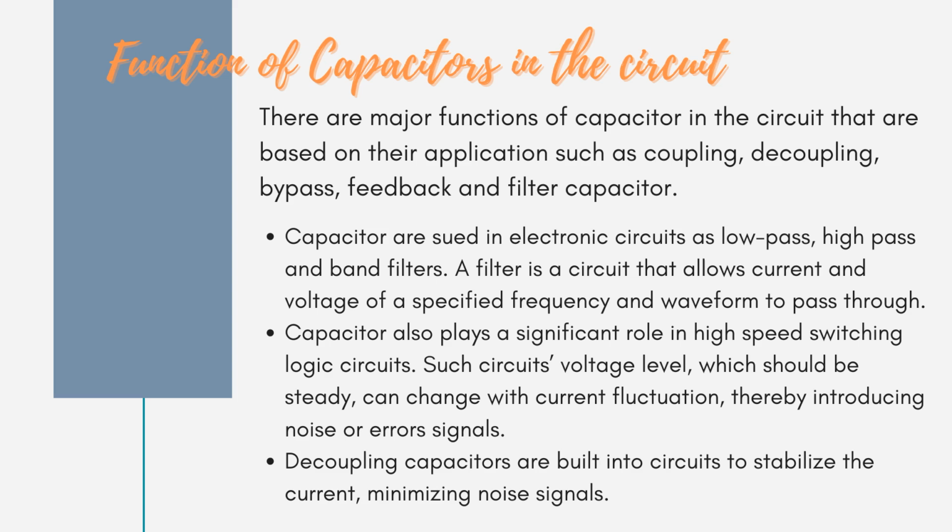1. Capacitors are used in electronic circuits as low pass, high pass, and band filters. A filter is a circuit that allows current and voltage of a specified frequency and waveform to pass through. 2. Capacitors also play a significant role in high-speed switching logic circuits. In such circuits, the voltage level, which should be steady, can change with current fluctuation, thereby introducing noise or error signals. 3. Decoupling capacitors are built into circuits to stabilize the current, minimizing noise signals.